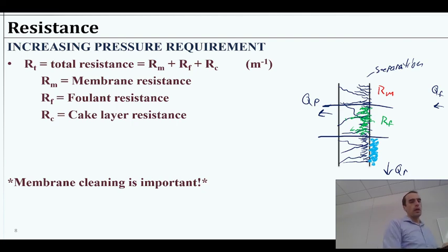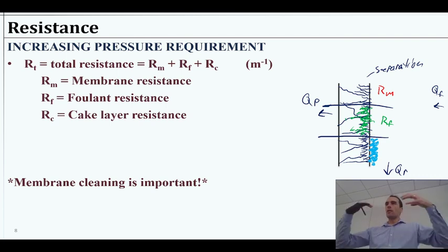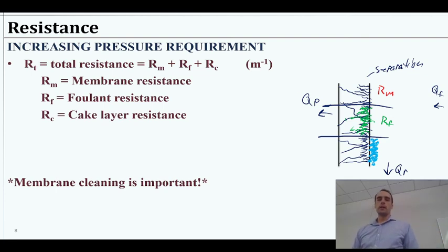And then for some filters, every few months or maybe once or twice a year, you'll take it and chemically clean it with some acid-base steps, maybe with some sort of detergent or bleach, temperature, whatever your membrane is capable of handling, and whatever does a good job removing resistance that tends to gather on that type of material. And that will restore a lot of this interstitial fouling, the RF here. Whereas backwashing typically does a decent job taking care of the cake layer.